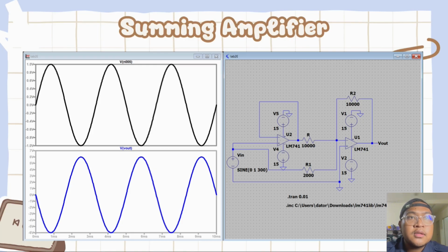This is caused by the op-amp slew rate constraint, which limits the maximum rate at which the output voltage can change. Finally, a key constraint identified is the inherent trade-off of the inverting amplifier, where achieving a high predictable gain comes at the cost of a low input impedance determined directly by R1.